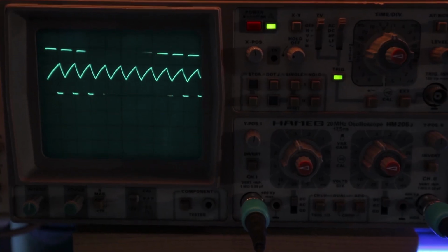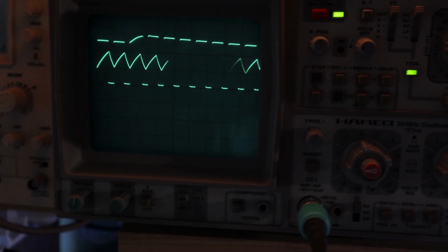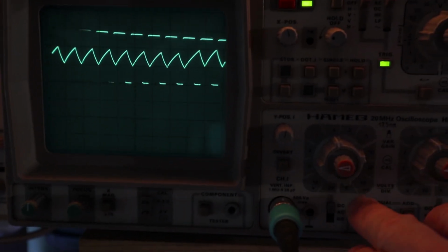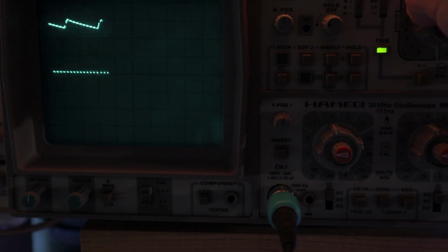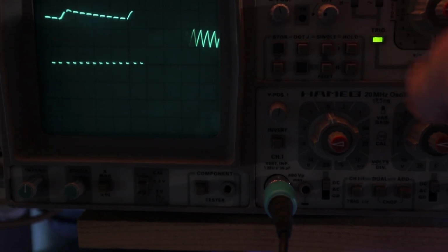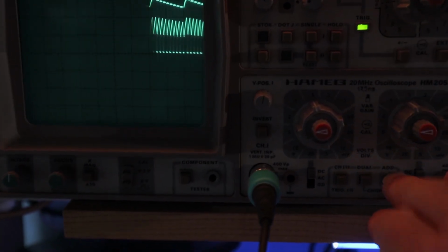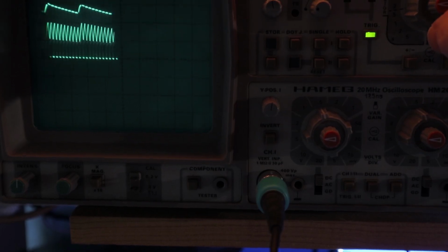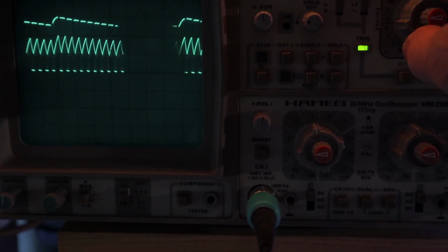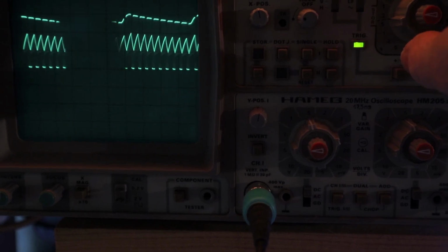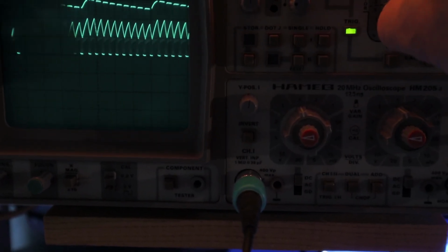For example, here in our test circuit I've simulated a fault condition where the power supply presents a strong AC component. The signals are heavily affected by this superimposed AC, and triggering on either channel while holding stable the square and the triangle waves, it is unable to hold the superimposed frequency, which therefore is uncorrelated.